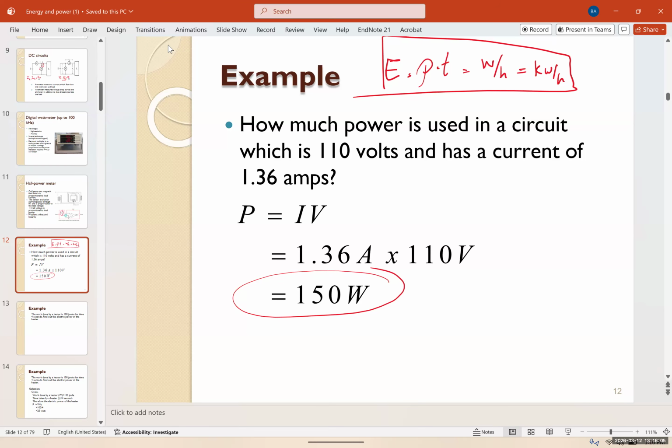So, for example, if you have a washer dryer that is turned on for half an hour and it's 4 kilowatt, then your power consumption for that would be 2 kilowatt hour, because you use the washer dryer for half an hour, 4 kilowatts times half, it's going to be 2 kilowatt hour. This is the way that they measure it. And the power generation is the same as well. When they want to pay a generation company, they measure the kilowatt hour and they do it per year.